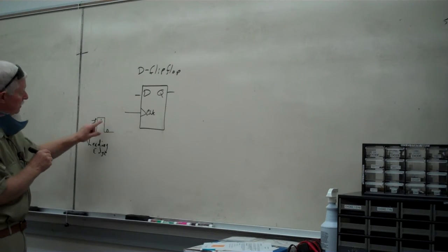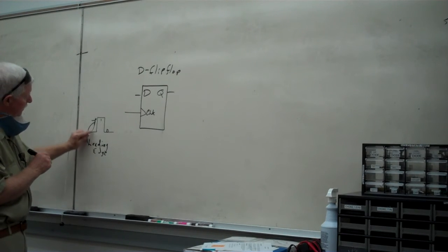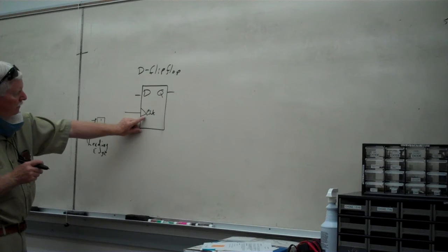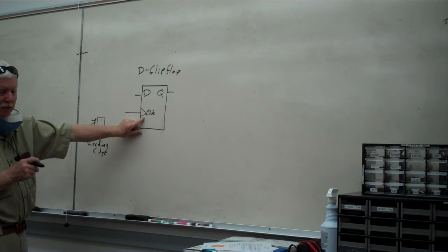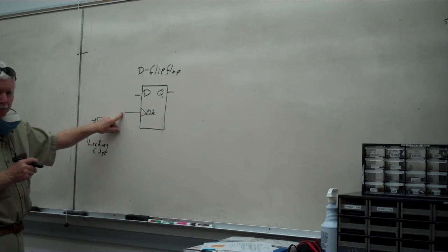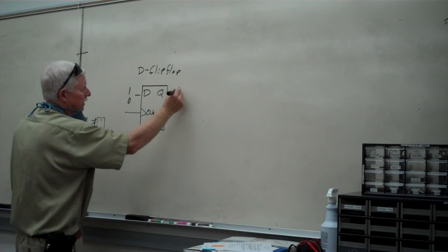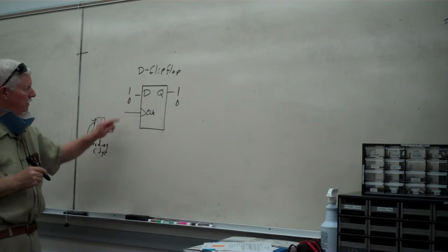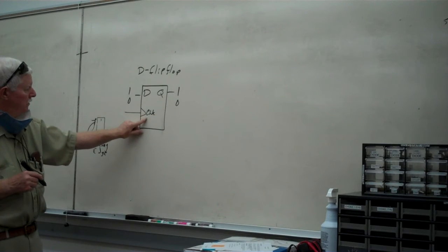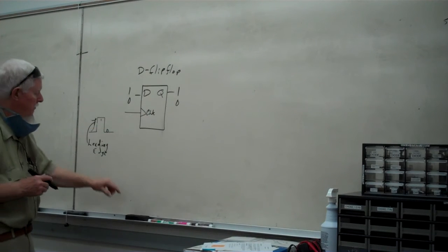Now, this particular circuit doesn't require the logic high for any particular period of time. It just requires this leading edge on the clock pulse to be present. It has a very particular type of circuit in this part right here, which enables us to activate on the leading edge or positive going transition of the clock pulse or control pulse going into this device. Again, this takes logic 1 or logic 0, and it transfers it out in the same fashion. It's not inverted. If 1 goes in, 1 goes out. 0 goes in, 0 goes out. So this is pulse triggering circuitry that's being used on these types of inputs.